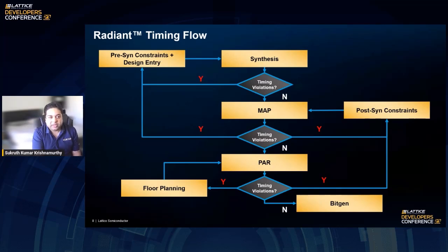are timing failures, then you will also have to go back to your RTL to see if there's anything that you can do to fix those timing violations. Our timing report usually tells you if the failing path is a logic-intensive path, or if the failing path is because of the placement and routing. At the post-synthesis stage, the design is still not placed and routed, so all the placement and routing data will be an estimated value. Hence, if it is a logic-intensive failure, then users can always go back to your RTL and fix the timing violations.